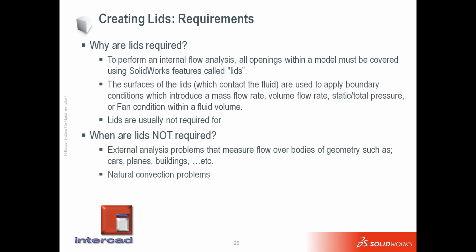The surfaces of the lid are used to apply boundary conditions, where we can have various conditions such as mass flow rate, volume flow rate, total pressure, fan condition, and so on. So obviously, if we don't have an internal flow analysis, for example, if we have an external flow analysis, there is no need to create a lid.